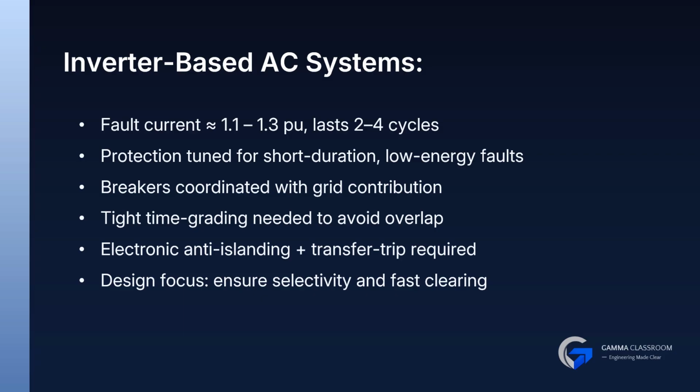Because the fault energy is lower and short-lived, protection devices must be tuned very carefully, especially the instantaneous region, to avoid miscoordination. Time grading becomes much tighter, and curve overlap is a real concern.